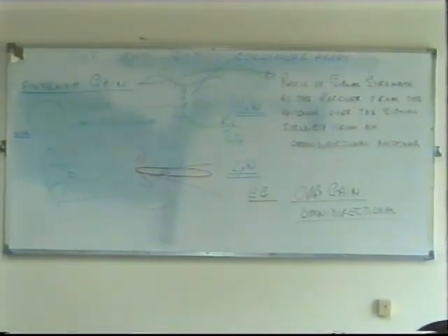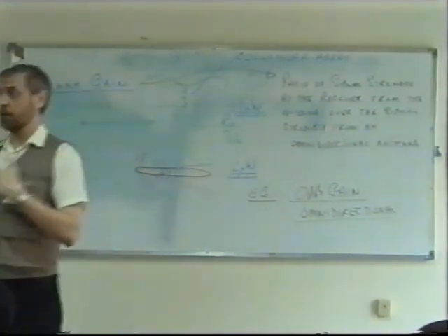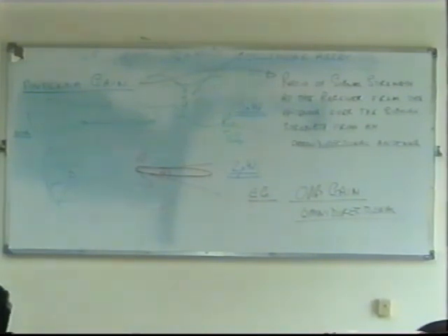40? I was trying to look for a figure in the book and couldn't find one, but I would think about that sort of figure, 30 dB. So you're talking about a very directional antenna. For the sort of communications we use in microwave point to point, we're talking about a few milliwatts of transmitted power. That's all we need in order to get communication.